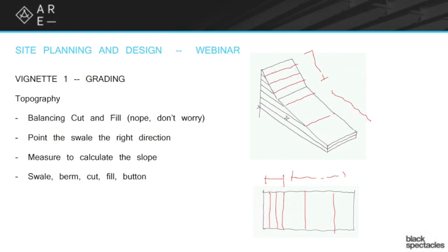One other quick thing to say about it, the contours are just a useful way of understanding the lay of the land. They are not meaningful other than that. There is nothing sacred. When you see a contour line, it doesn't exist in the world. It's a made up concept. It's an abstract idea. You'll find people often start lining up sidewalks with contours, or putting the building against the contour line, because it just seems like it should be meaningful. It's meaningful in terms of the lay of the land, in terms of the shape of the land, but it's not meaningful for any other reason.